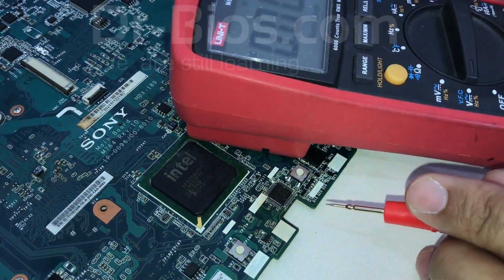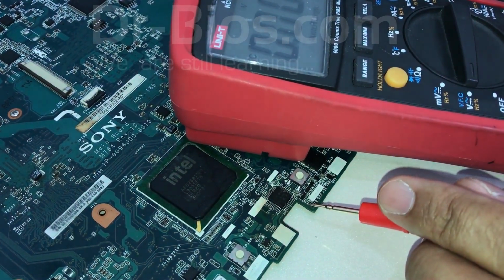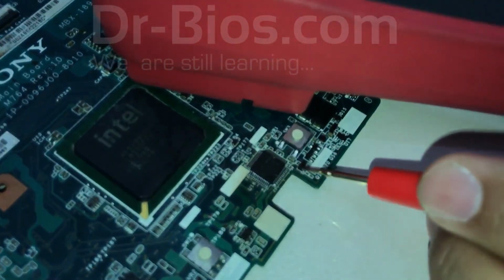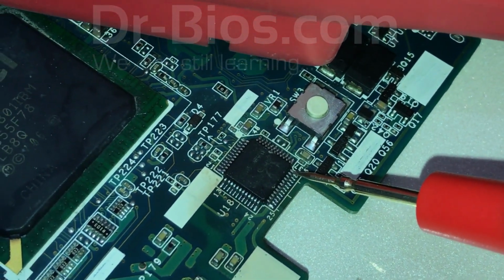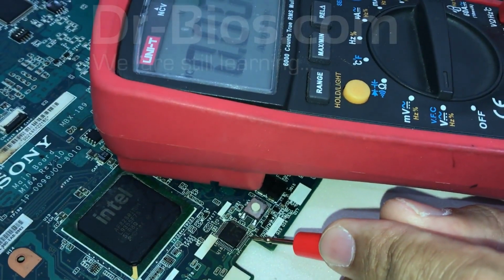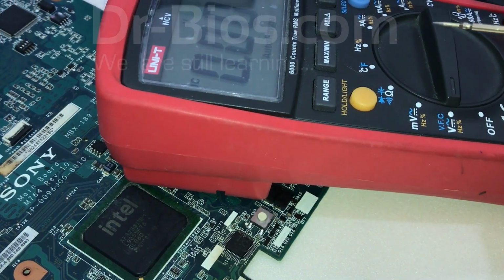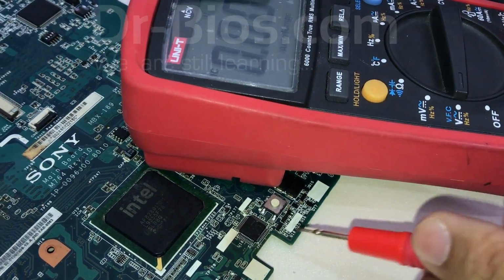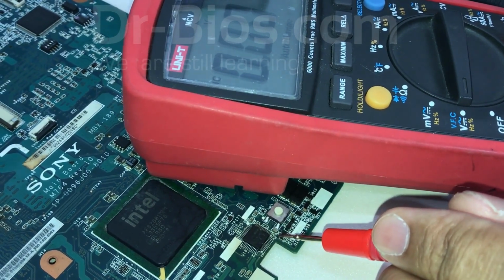I should say something that I didn't mention during the video, and I think it's necessary to be said. Pins 35 and 36 of this IC. Take a look. I've tested this before, but I didn't mention it in the video. Around 2 to 2.5 volts should be the output of these two pins. These are the output signals of this IC, which are connected to the amplifier signal input, which means sound is transferred to the amplifier from this IC. Then it is transferred to the speaker. This means you can test these two pins before testing power of this IC, and that's enough.